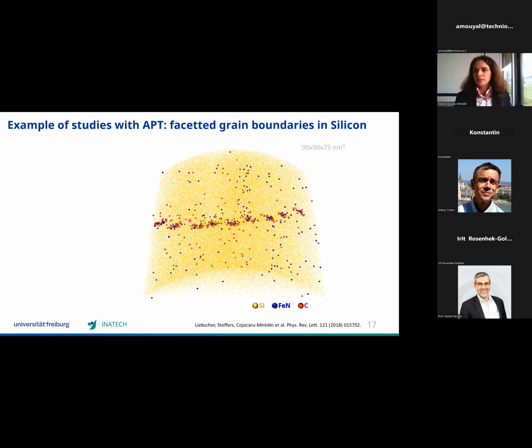Multicrystalline silicon is used for solar cells. We know that the highest efficiency for a silicon solar cell is 27%, but this is obtained for single crystalline, not multicrystalline. But for industry and for application, single crystalline is much more expensive than multicrystalline silicon. So why can we not use multicrystalline silicon for solar cells? We could use it, but the problem is that the efficiency is much lower, and we could observe that the reduction of the efficiency is mainly obtained at the grain boundary, and this reduction is due to the recombination